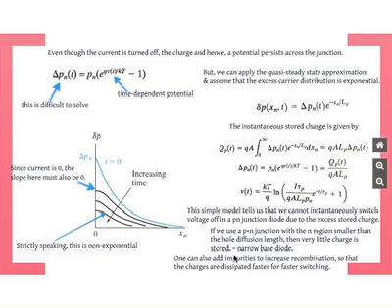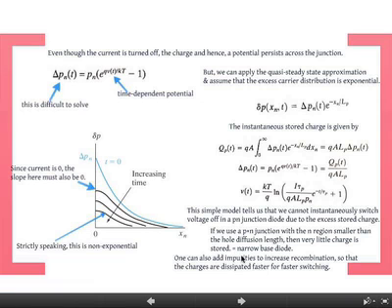Then very little charge is stored, because this distance is small. Okay, that integral 0 to x is smaller. Lower charge is stored. Of course, the less charge is stored, the faster it is to discharge it or recombine, essentially. So you can make it faster. Okay, and this particular device is called a narrow base diode.